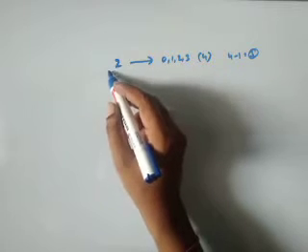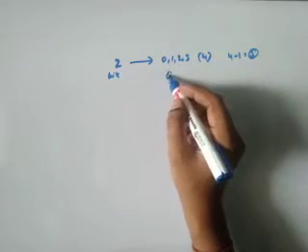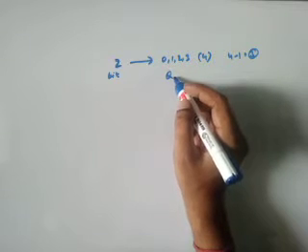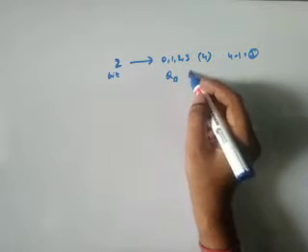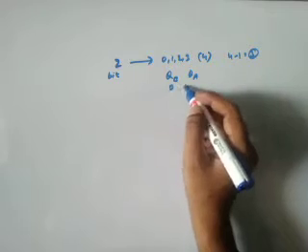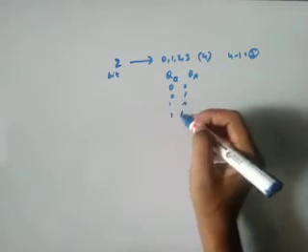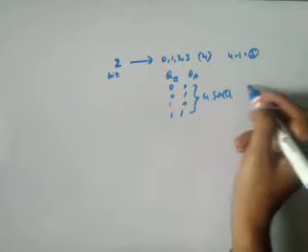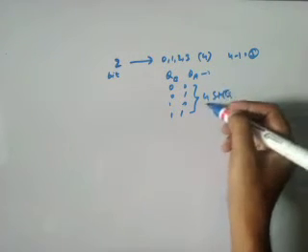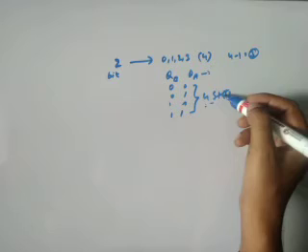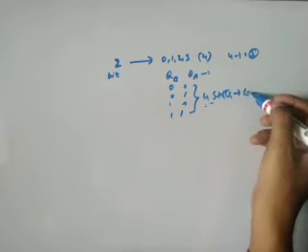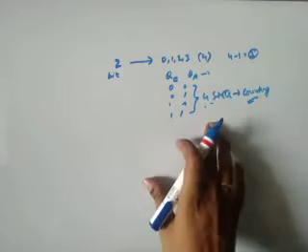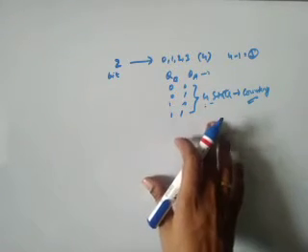I call it a 2-bit counter because you have two binary bits, and the states for QB and QA are 0 0, 0 1, 1 0 as well as 1 1. So in total you have 4 states. A 2-bit counter will have 4 states, and these states are nothing but your counting. This is the way any counter works.